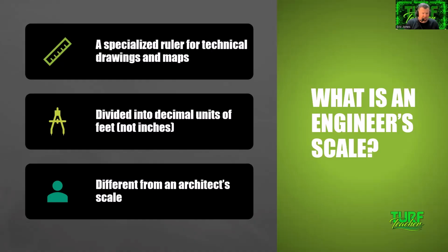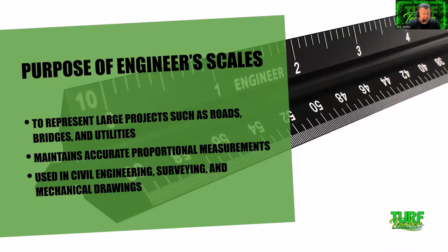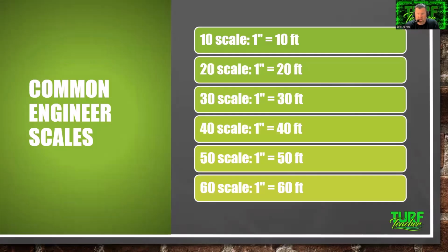It's divided into decimal units of feet, not inches, and it's different from the architect scale. The purpose of this engineer scale is to represent large projects such as roads, bridges, and utilities, maintain accurate proportional measurements, and it's used in civil engineering, surveying, and mechanical drawings. And of course, landscape architects and irrigation designers will use it probably just for site plans, their base plan, and their master plan, not for construction details. Excuse me. Some common engineer scales.